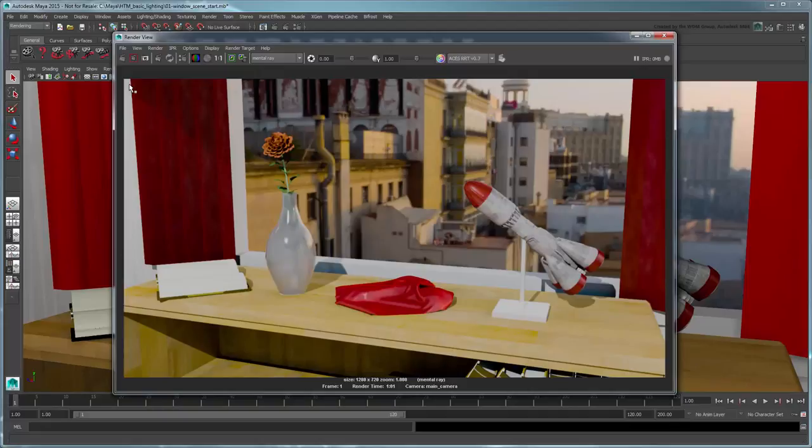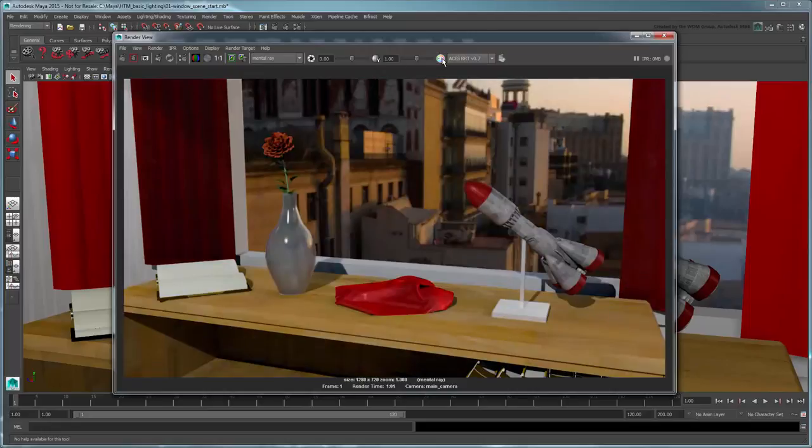Thus, we're actually getting a double transform. To mitigate this, turn off the View Transform icon in the Render view to see what the transformed render actually looks like. Also note that while we're using the integrated mental ray renderer for this example, third-party support is also possible via the provided SDK. You're now ready to control the colors of your scene no matter where your render is going.